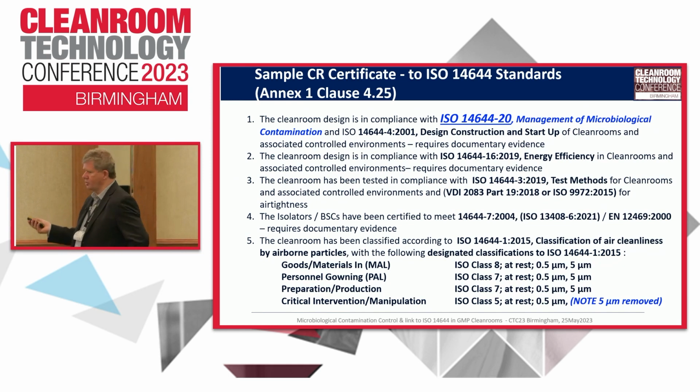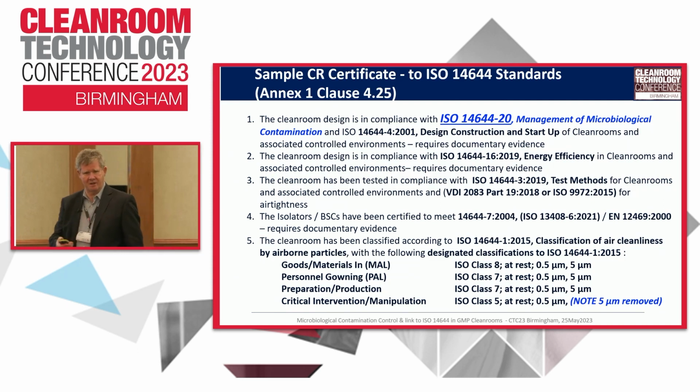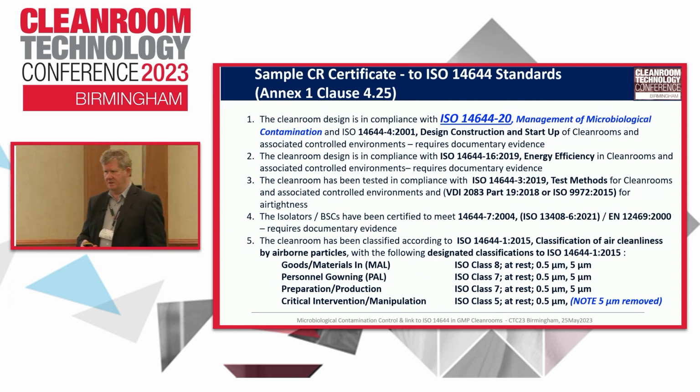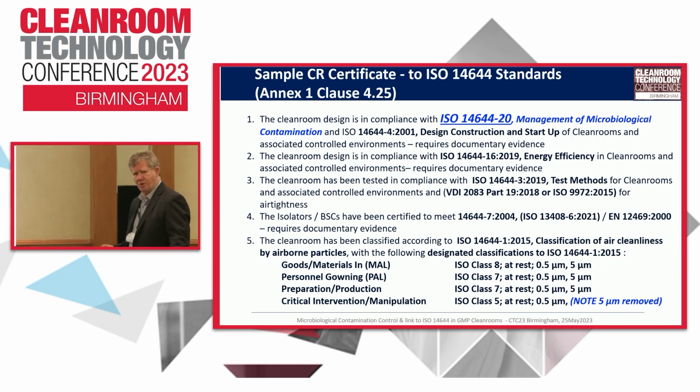One of the things I've been pushing in Ireland and elsewhere for many, many years is I don't want a clean room test report. And by the way, you're not a clean room validation engineer. You don't validate a clean room, you qualify a clean room. You qualify equipment and facilities, so read Annex 15 on Q and V. You validate a process or a product. If I have a cleaning equipment, I've qualified the equipment to clean, but I validate the process of cleaning. It's different, okay?